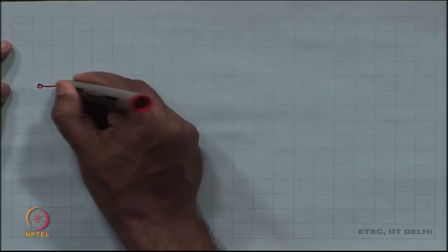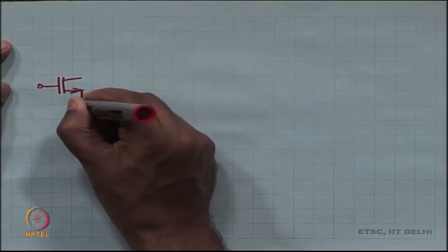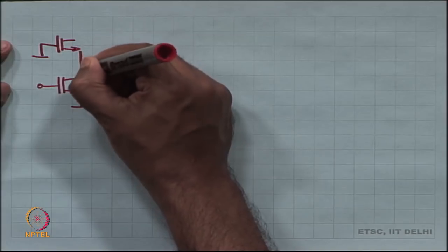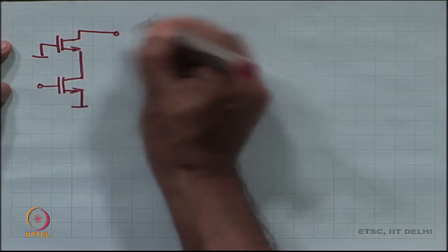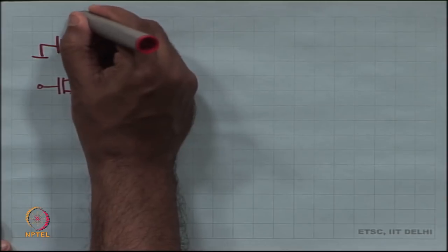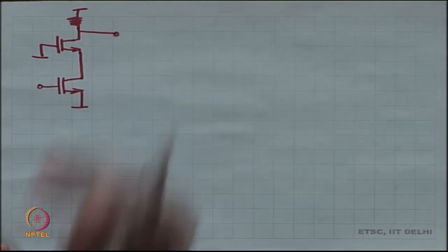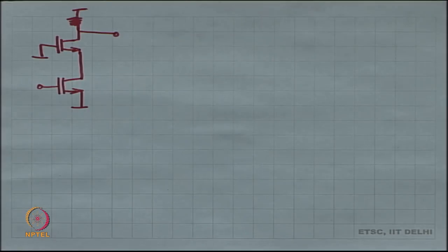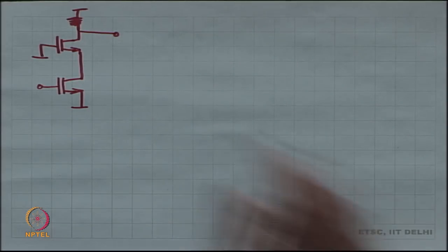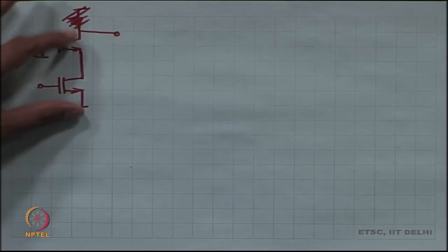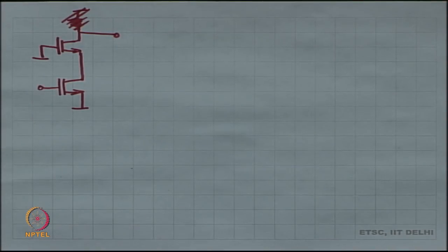As far as you remember, the cascode circuit, I am just drawing the small signal equivalent. We are going to assume that this resistance is so large that it does not really matter. So, let us say it is not really in the picture. Invariably, instead of that resistance, it is going to be another cascode with PMOSes, so it is just going to double up.